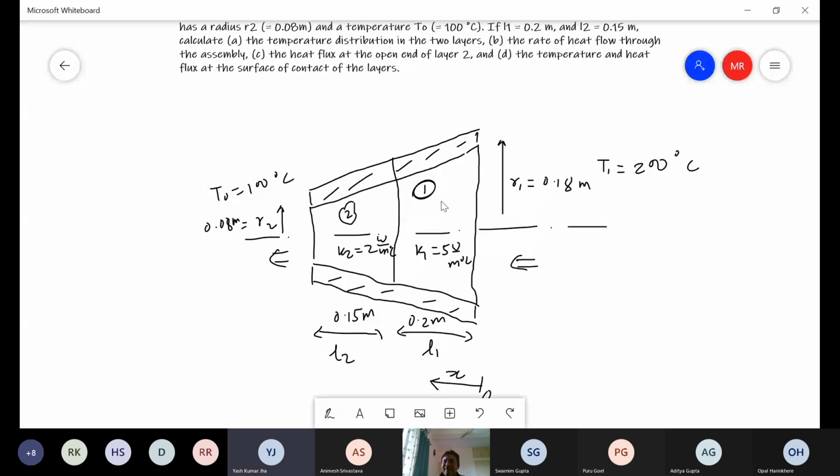No, sir, I'm actually talking about Qx only, the heat flow that is going in the X direction, but its value, why is it uniform for this cross section? If we take a particular X, if we vary R, why is it uniform for X? At a particular value of x, it is uniform throughout. That is what is being taken because there is insulation outside. But as we move along the x direction, it is varying with the x. So as the x is moving, your cross sectional area is decreasing, isn't it? And therefore your qx value is going to change because your capital Q remains constant.